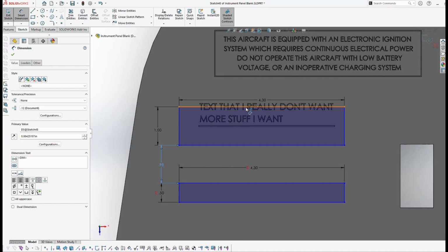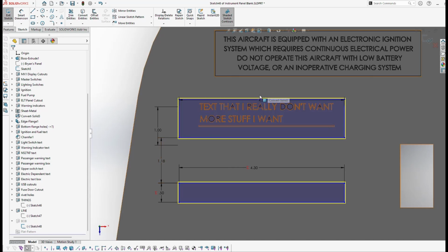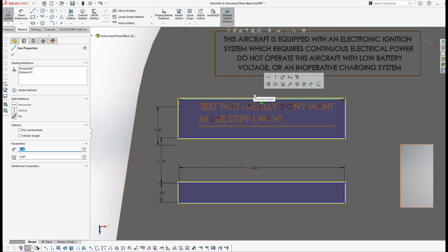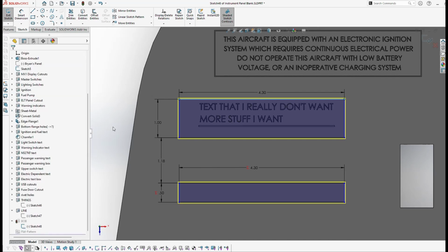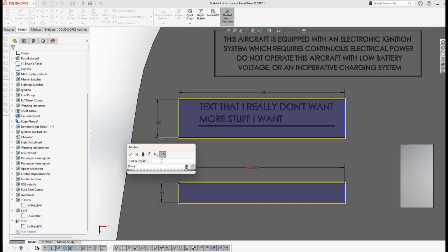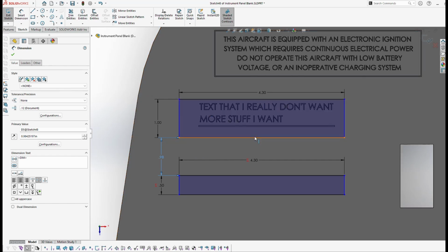Now an unintended consequence of this is another teachable item. I'm going to hit Control Z and I'm going to get rid of that. If I want things to not move, I can click on this line at the top, for example. I don't want that to come down. Again, intuitive nature of SolidWorks. The anchor fixes things so they don't move anywhere. Now if I change this to 25 millimeter, done. When things are fully defined, they turn black.